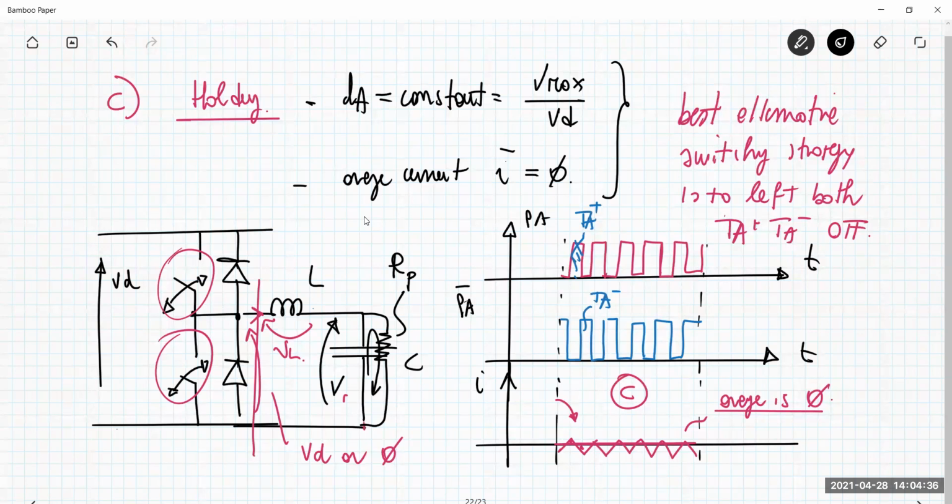So this means that from time to time, I have to close the switch in order to provide a burst of energy flowing to the capacitor and refreshing the voltage across it. So basically, I have to leave both switches open, but from time to time, I have to refresh the charges in the capacitor that otherwise will be lost due to this kind of behavior.